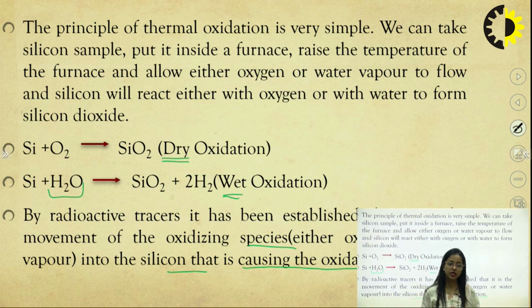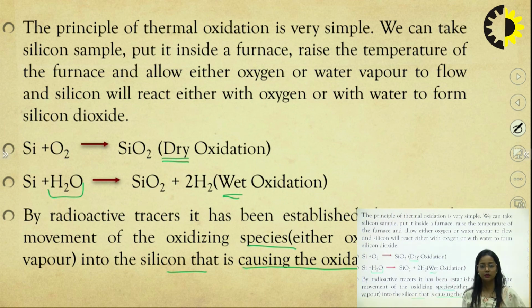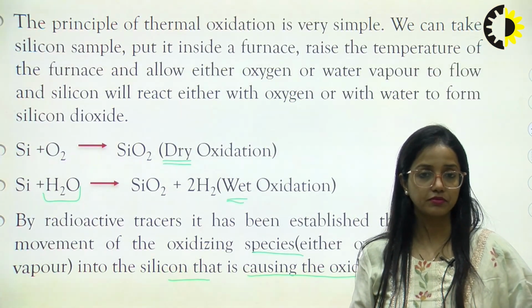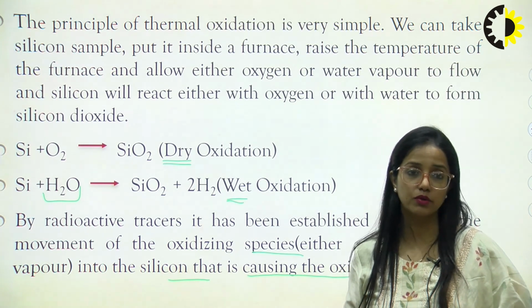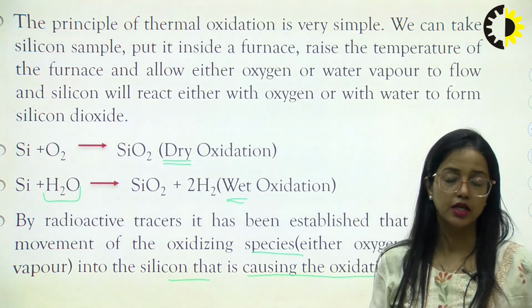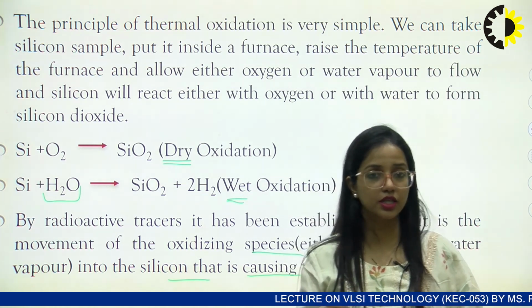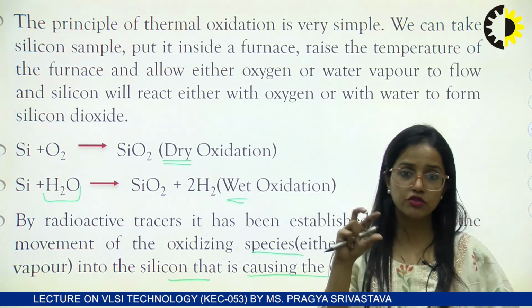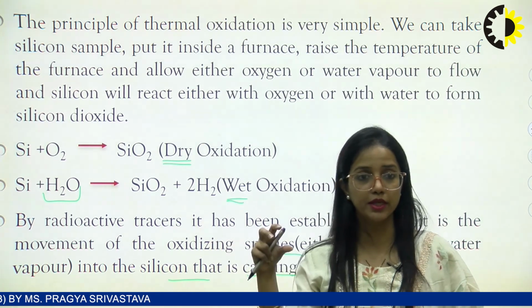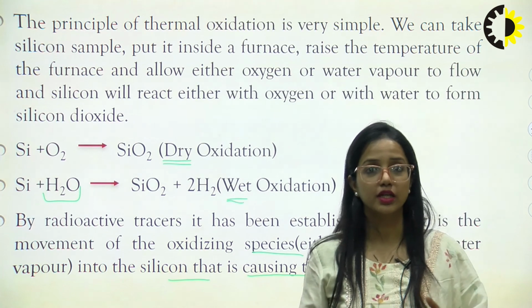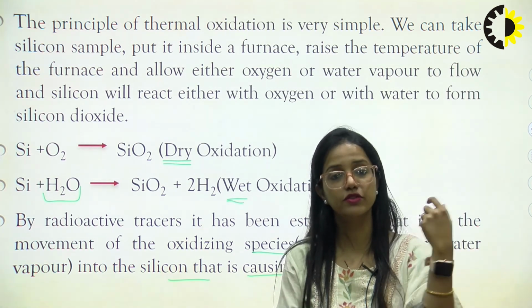Moving ahead, we have seen how oxidation helps in making P wells and N wells in an N-type substrate of the body. Making those wells only at particular places can be achieved only with the process of oxidation, where the oxide will shield the remaining portion where we do not want the dopant to settle on the surface of silicon.